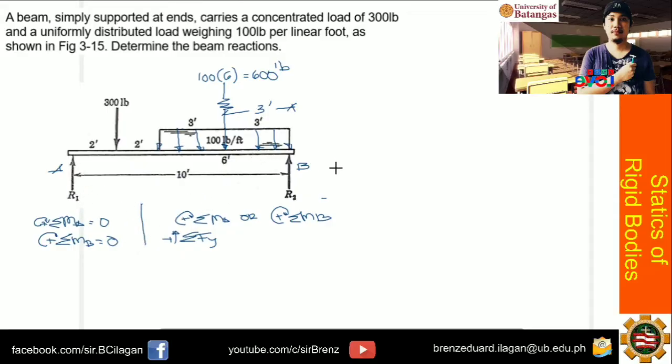So I will start with option 1. Option 1 takes both summations of moment. So let's take moment at point A. When we take summation of moment at A equals 0, the forces will rotate about this point. So what forces do we consider? Again, this 300 pound load, this 600 pound load, and the reaction at B, at point B.